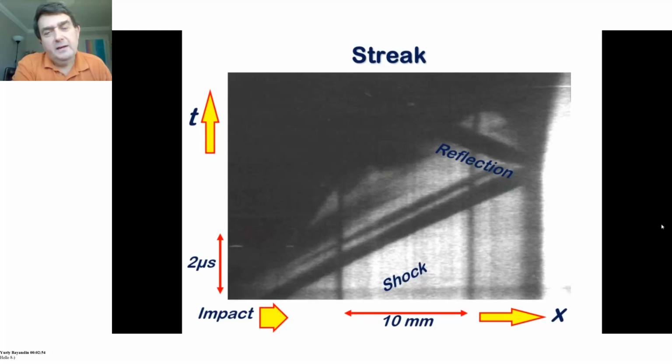We can see a kind of dark region behind the shock wave. We can see a very cloudy region developing as well. So processes such as the growth of that failure wave, or failure front, are occurring in that region. So this is the initiation of the failure wave, and here the failure wave is getting very strong. Now, at some point, it all goes very black because of all the cracking in the sample, and we don't see very much. So we lose detail, but at least we've seen the velocity of the shock wave, the reflection, and got an idea of the velocity of that failure front.